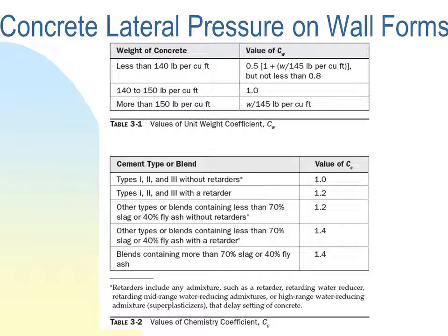However, the other factor, which is very important, is mainly related to the issue of admixtures. So whether you use admixtures or not. If you don't use admixtures at all, then the factor is simply 1, which is the case in most of the cases that we could see. However, if you use chemical admixtures, retarders or superplasticizers or whatever, the factor will be 1.2.